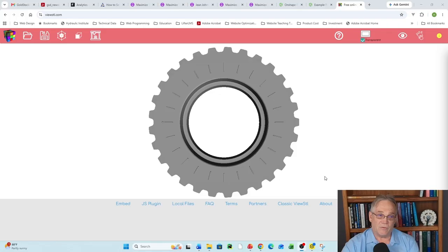What's important here is that the teeth have to be fairly accurate in order to get the meshing action, but also in order to get where it's done repeatedly, it needs to be fairly strong as well. And thus it's important to orient these parts correctly within the machine in order to both get the meshing accuracy as well as the strength of the components.